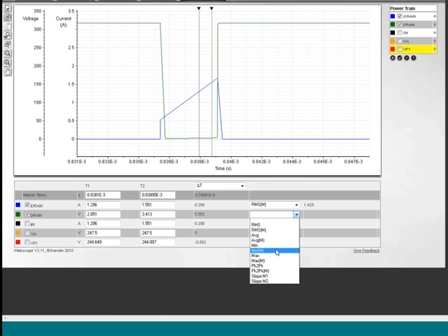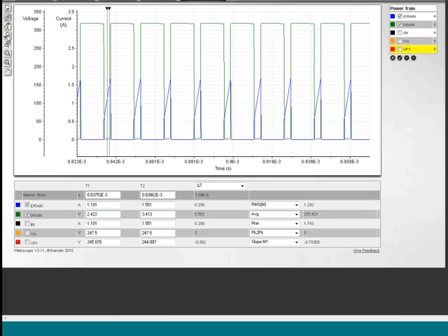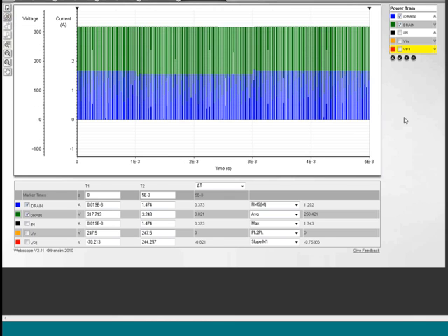I have full measurement capability for each of these. I can do averages, maxes, peak to peak, and I can look at the slope between the two cursors. So quite a bit of measurement techniques. And you'll notice that when I was on this tool, I was zooming into the waveforms. If I ever need to get back to a different zoom level, I can go back one zoom level, which takes me back to where I was, or I can reset the zoom level to the basic default value that came up when the part came available.